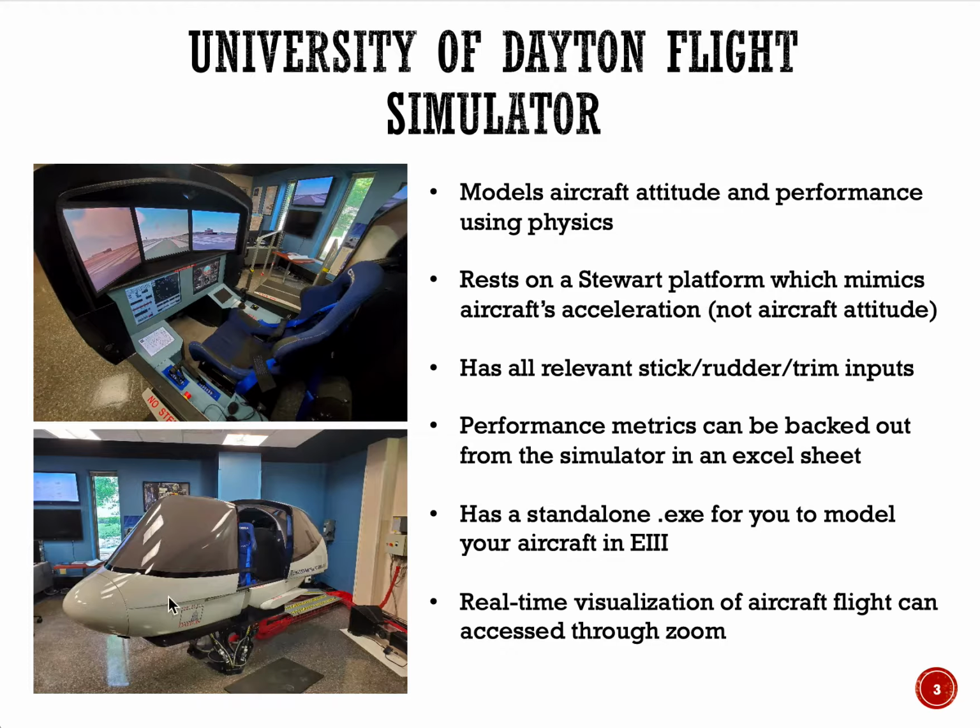And the simulator actually rests on top of a Stewart platform, which mimics the aircraft's acceleration, not the aircraft attitude. When you sit inside the cockpit right here, close this door, and then turn the motion on, what you really feel is the acceleration. The simulator tries to mimic those accelerations by finding those acceleration quantities from the equations of motion, right? It doesn't necessarily mimic the attitude, but it mimics the acceleration, right?